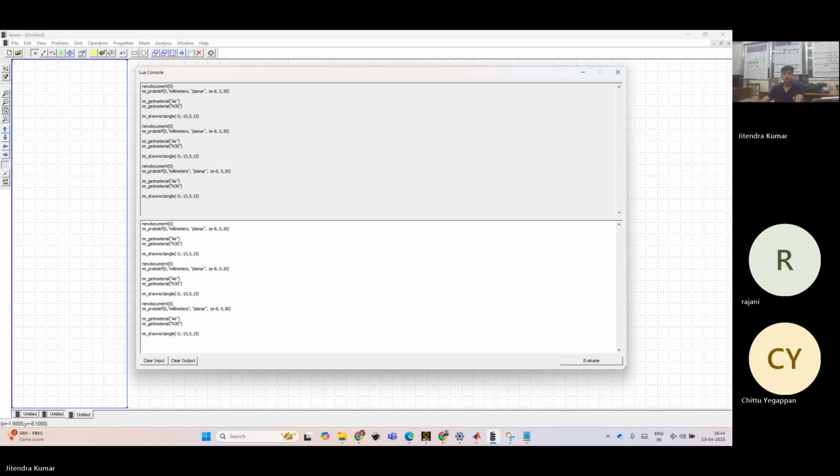Now we have to create a label, then set that label, give the magnetization, and assign properties, right? So we will do all these things. First, we will add a block label. A block label means we are going to assign a permanent magnet, so we are making this rectangular block a permanent magnet.